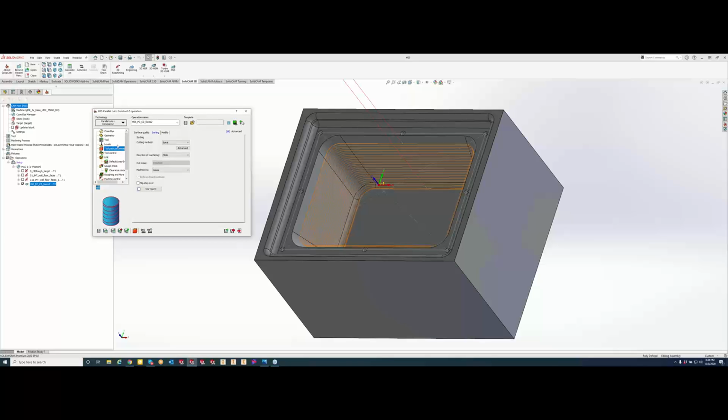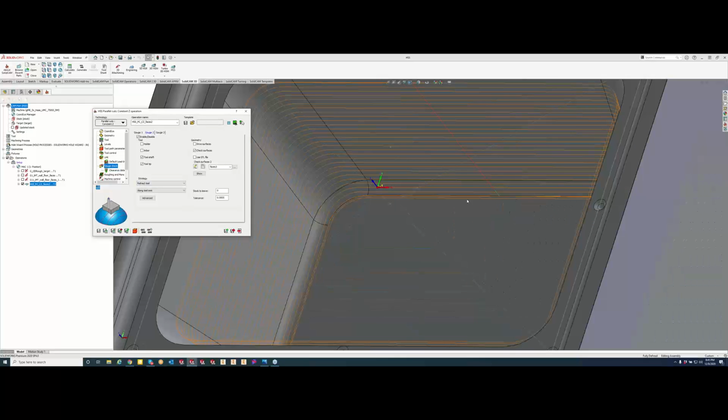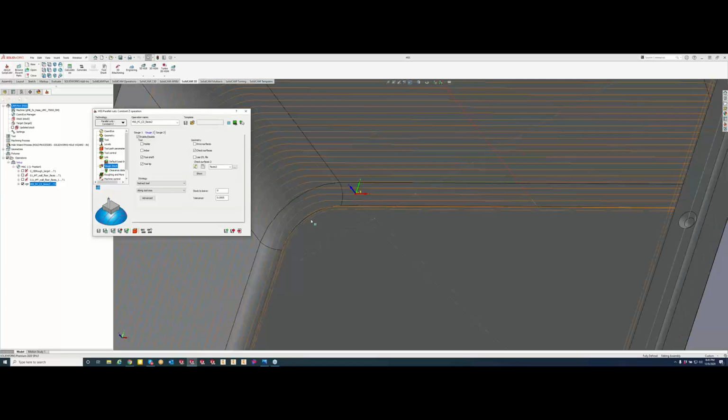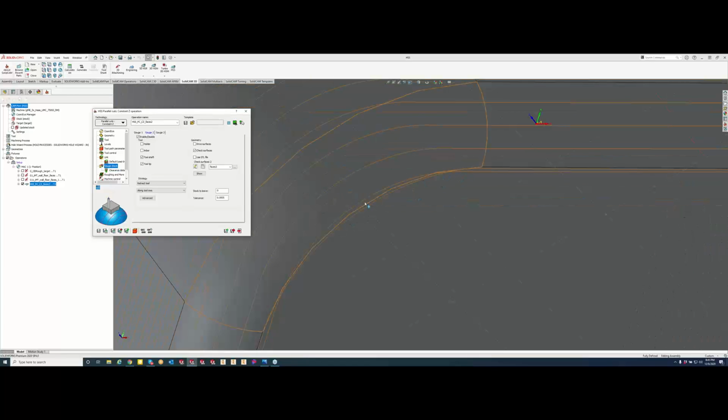Yeah. Before we jump into cleaning up the surface finish, let's go back to the gouge check, because this is actually a really good example of what's going on with the strategy there. You can see that you told it to retract the tool, so it makes another lap down there at the bottom, but it picks it up off that floor in Z. I don't know if maybe you can zoom in there and show that. In those corners, you can see what looks like overlapping lines where it's actually picking up that tool in Z and making another lap around.